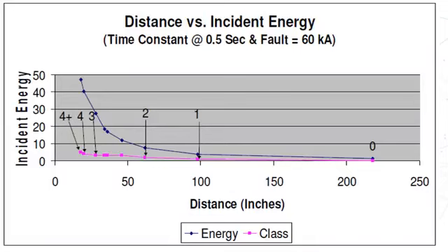You are reducing the working distance from 36 inches to maybe 18 inches. So the PPE which you are wearing to perform the thermography might not be suitable for that particular task, and you might also not be a qualified person to perform that repair or replace task. So you have to pass this on as a new job. A new risk assessment will be performed, and the PPE and other things will be selected according to the task at hand. That falls under the scope change.